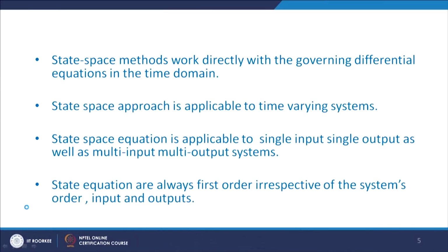Third, state space equation is applicable to single input, single output, as well as multi input, multi output systems. In practice, most of the systems are multi input, multi output. Therefore, we should have techniques of stability as well as control design which are applicable for multi input, multi output system. So that type of approaches, particularly stability and control design, are easily available in a state space approach, whereas it is very cumbersome in case of the classical approach.